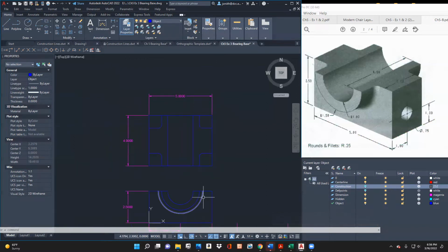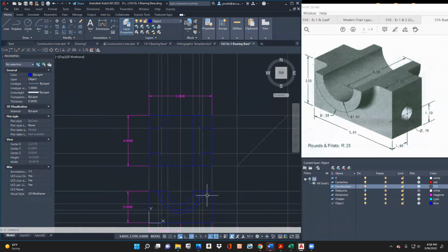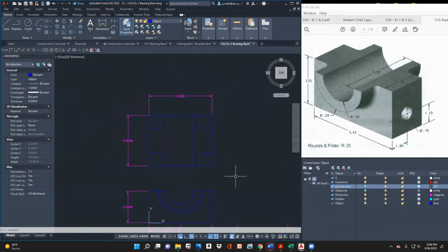And so you'll notice that's the radius. If I turn the construction line on, you'll see that's what we're seeing. All right, so turn the construction line off there. Now I don't need this line here, so let's go ahead and do trim again. And again, it's hard when you've got the construction lines because it will stop where the construction lines are. So that can be rather challenging. Okay, I think that looks good.